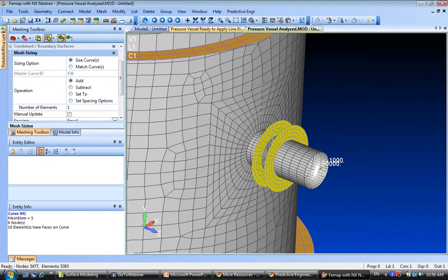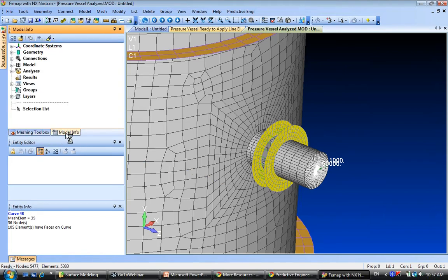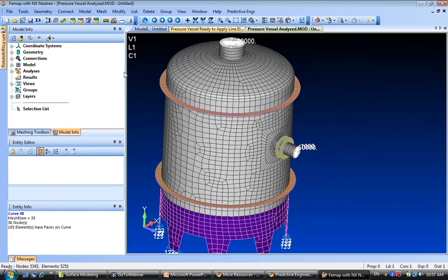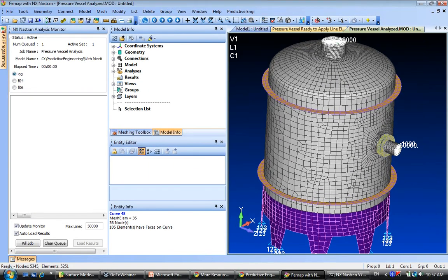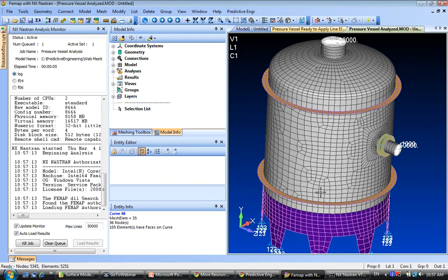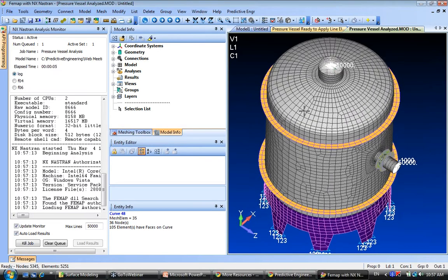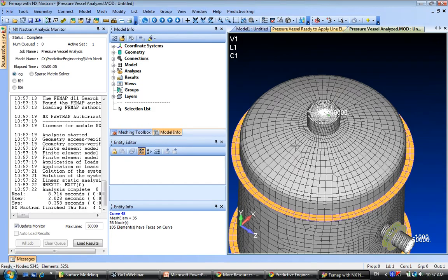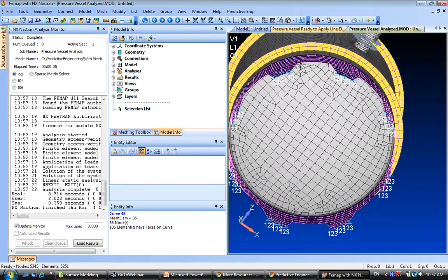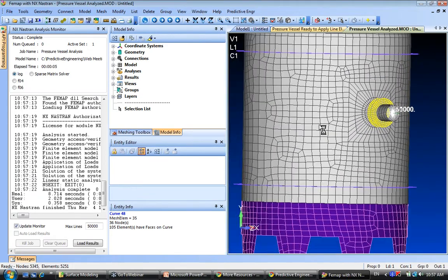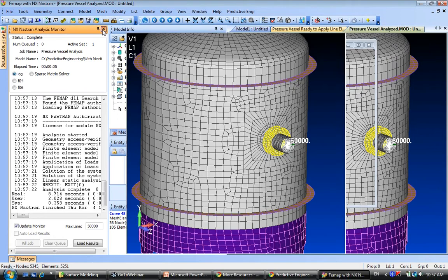I could make it a lot tighter because that's a pad around a curve, things like that. But I don't want to do that because I have pressures applied on the back. Yes, it's not the prettiest mesh there. I do have other things to do, but that is very, very nice. I mean, this mesh took me no time. I just basically threw it together, and I could clean that up too.